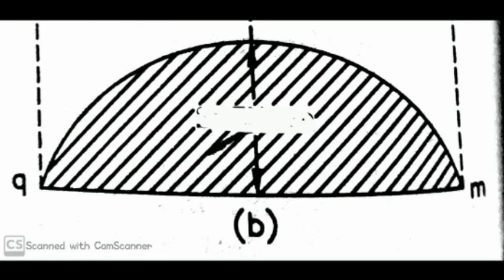Here we see that the BM is of curved nature. Why is it curved? Because in a simply supported beam, if the load is UDL, a uniformly distributed load, the BM is parabolic in nature, not a straight line. So when you draw the BM diagram, you have to draw a curve. When you show the SFBM diagram, first show the loaded beam, after that the SF diagram, after that the BM diagram.